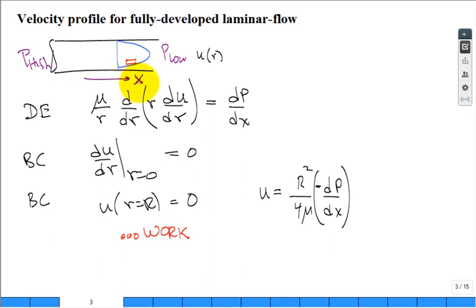And so the pressure gradient is from high to low. It's like a negative slope, so we put a negative on there, so this term is by itself positive. And then we finish out this equation. It's 1 minus lowercase r over cap R squared. That's how you get the quadratic nature of it. Then you check the equation and it works.